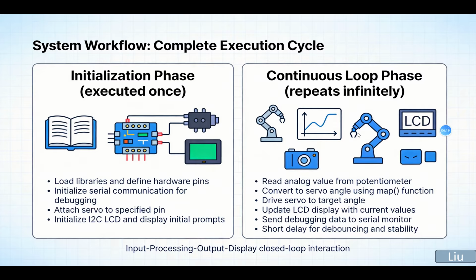The initialization phase: load libraries and define hardware pins, and initialize serial communication for debugging, attach servo to the specified pin, and initialize I2C LCD and display initial prompts.